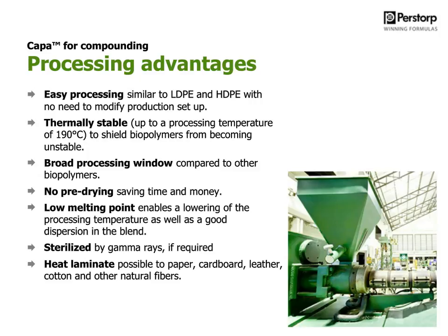And if we think about addition levels, working with, for example, PLA and films based on biopolymers, we usually suggest an addition level of around 20 to 30% of PCL in injection molded formulations, working with starch and PLA. And for films, for example, thermoplastic starch, we suggest to add around 15 to 30% of PCL to obtain an improvement in the properties, reduce the brittleness, and introduce elongation into your films that you're making.